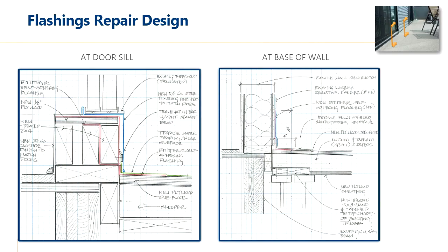Following the wood structural repairs, we had to dig into flashings, as originally intended, of how to improve the sill flashings, specifically at the doors and adjacent, to improve this issue so it didn't occur again. Here you have two normal two-dimensional details below the doors and at the base of the wall.